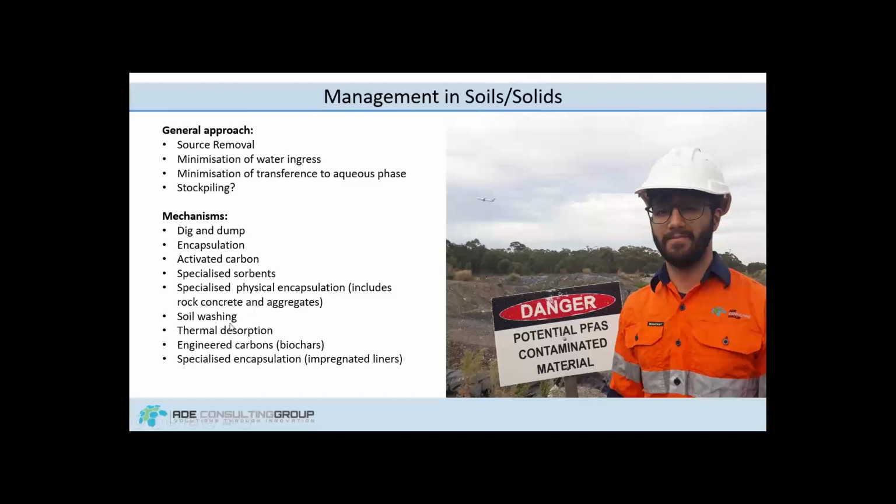I'm not too sure where it's at the moment with getting PFAS levels down to very low levels, but obviously this is a good way to remove certain PFAS congeners from soil. Thermal desorption obviously has been used a lot in the contaminated land industry for removing and destroying contaminants. The benefit of removing and destroying contaminants is that we no longer have the risk, and the risk has been completely removed rather than managed.